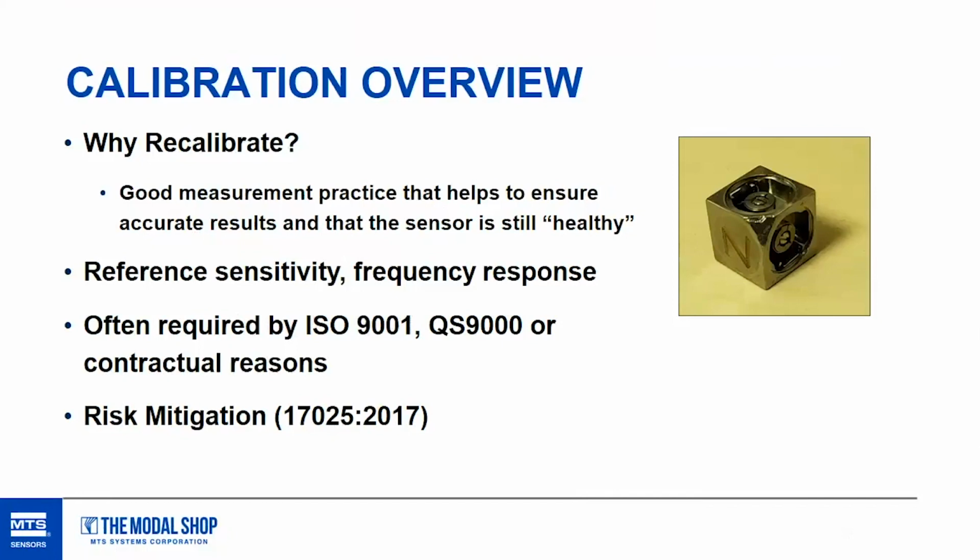If you don't know what's been happening to your accelerometers, or you need to know what's been happening to your accelerometers, this is where recalibration comes in. It's going to be in the form of a reference sensitivity check in most cases, along with frequency response.